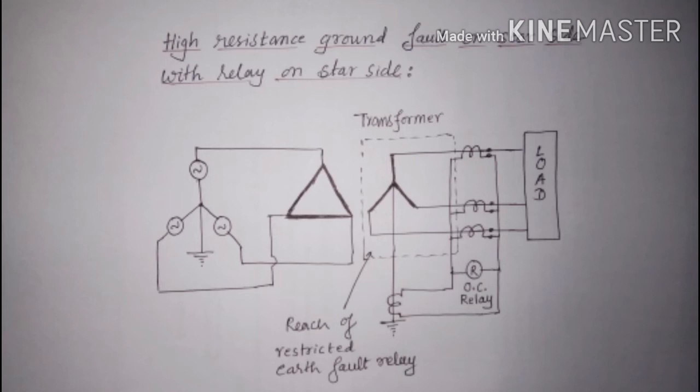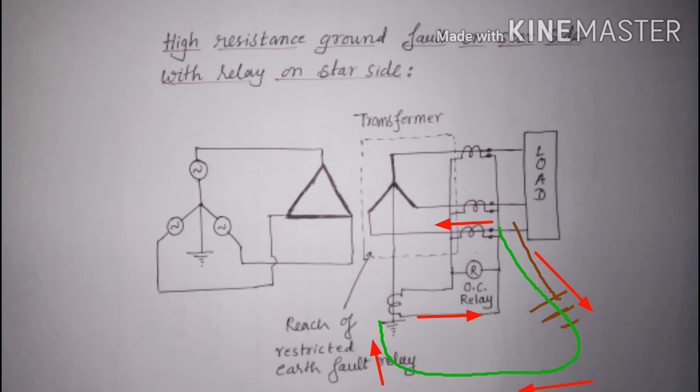If phase 2 ground fault occurs between the CTs and the load, then the fault current will flow through the secondaries of the CTs. However, the current circulates through the CT in the neutral path and the CT in faulted phase. Thus, no spill current flows and the scheme remains stable on external fault.